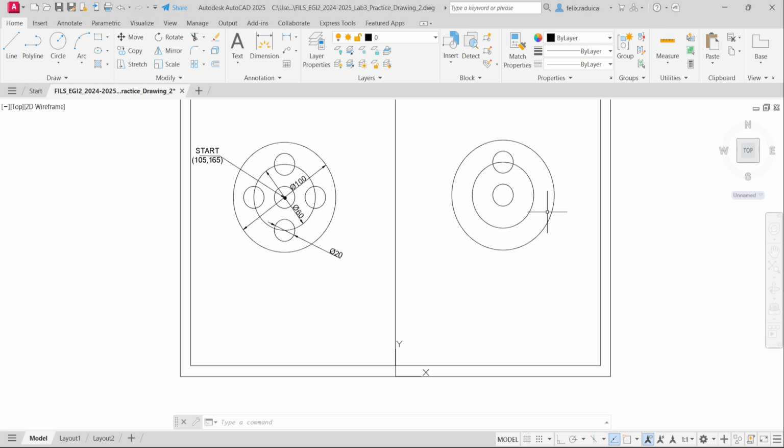Now all I have to do is go like that and do the rest of the 3 circles. So I will use the rotate command, rotate enter, click on this circle, enter, CEN enter to specify how to rotate from here, and I don't want to move it, I want to create a copy of it, so C enter for copy, and give the angle to be 90.